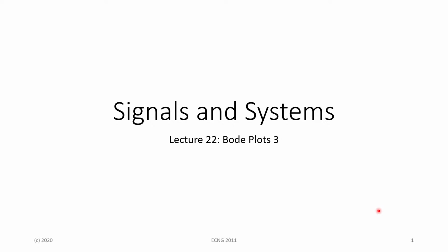So you need to observe the effect of this resonance here and how we accommodate it in the system equations. Or if we do encounter a system equation, how do we know that the system itself has some resonant factor in particular? This goes back to when we were talking about second order systems, where we had the damping factor zeta, and that's what's going to be playing a very important factor here in determining the resonance of the system itself.